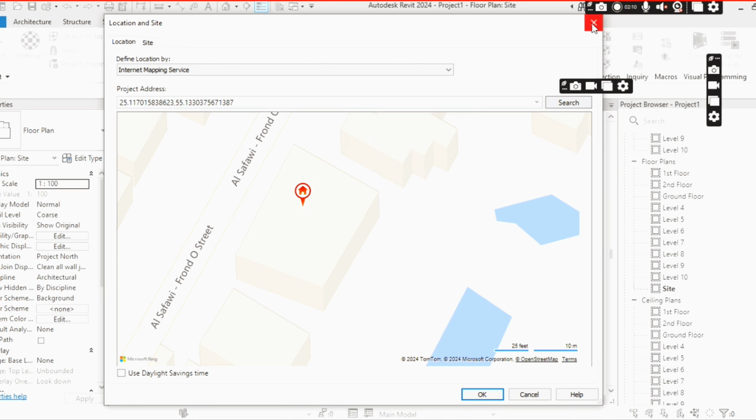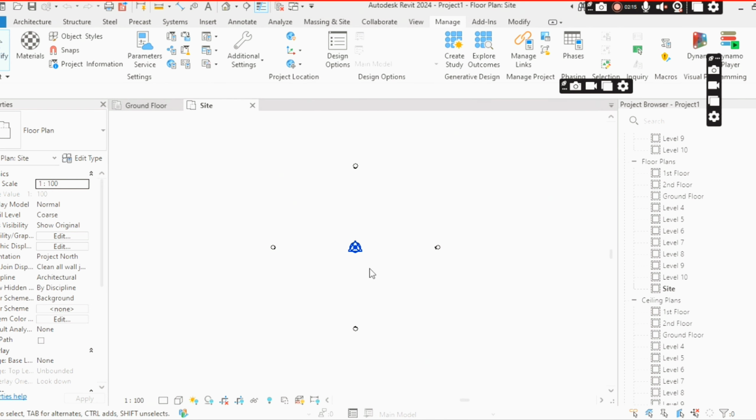So now further, after completion of this task, what do we have to do? Then we have to place the grid. And always remember, the grid you have to place at level 0, meaning Site. Site is the 0, or else you can go with the ground floor. Because when the mechanical people take the mechanical template, they never find the site plan here; they will never get it.